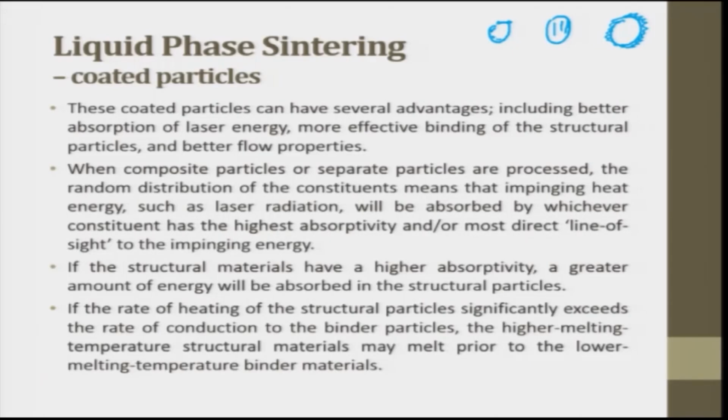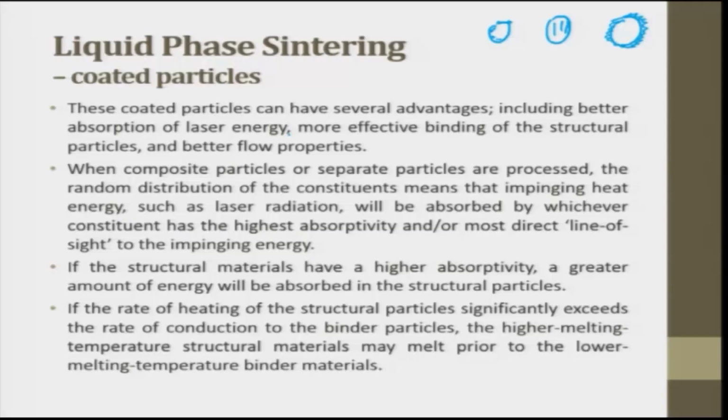So, you can have nickel with X percentage absorption, copper will not have the same percentage, cobalt can have higher, tungsten carbide which is used here need not have anything. So, depending on the absorption property of the metal or the particle we use, we can use it for the advantage of liquid phase sintering, including better absorption of laser energy, more effective binding of structural particles and better flow properties.